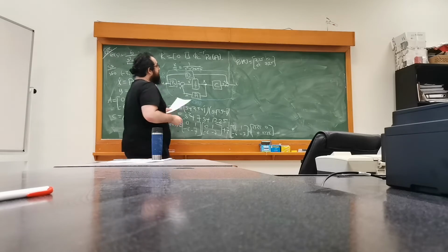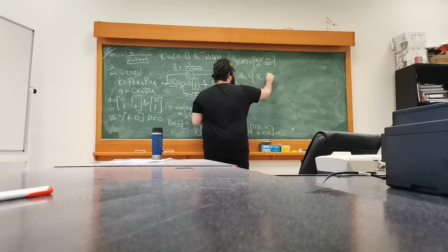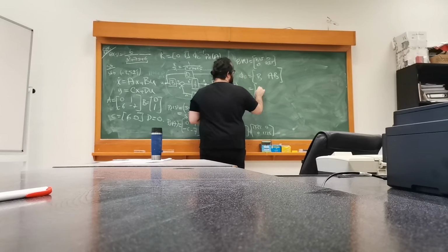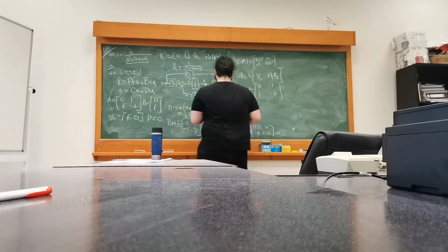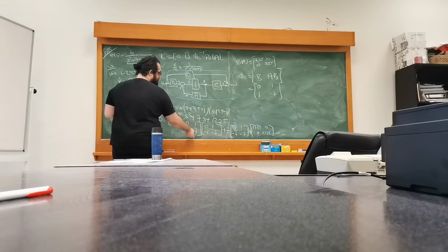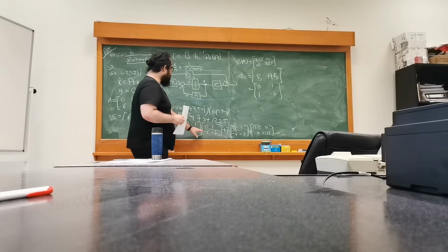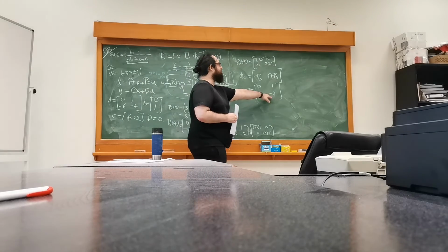And then we need phi c, the controllability matrix, which is B and AB. Therefore, we have 0, 1, 1, minus 7. It basically shows the second column here, because with 1, 0, 0, 1, 0 times this column, 1 times this, added up gives us this here.